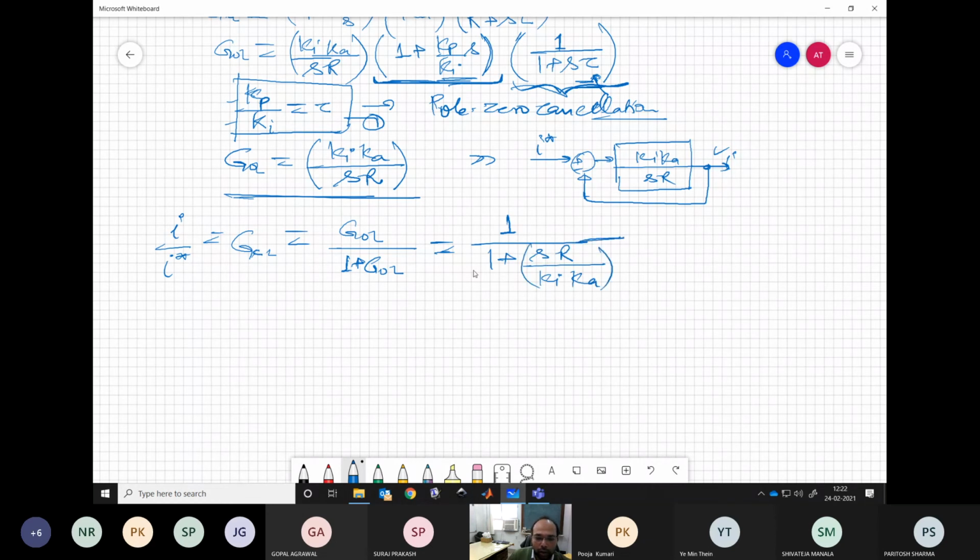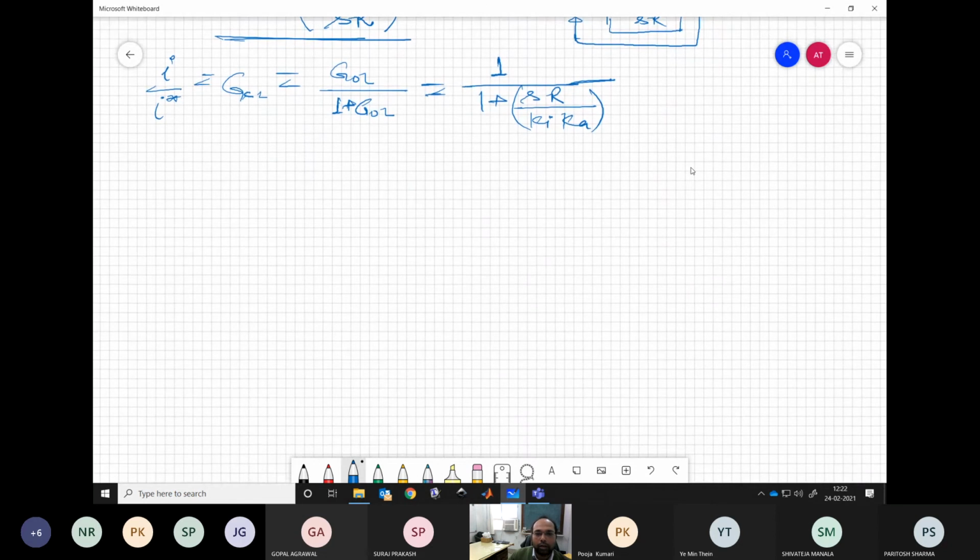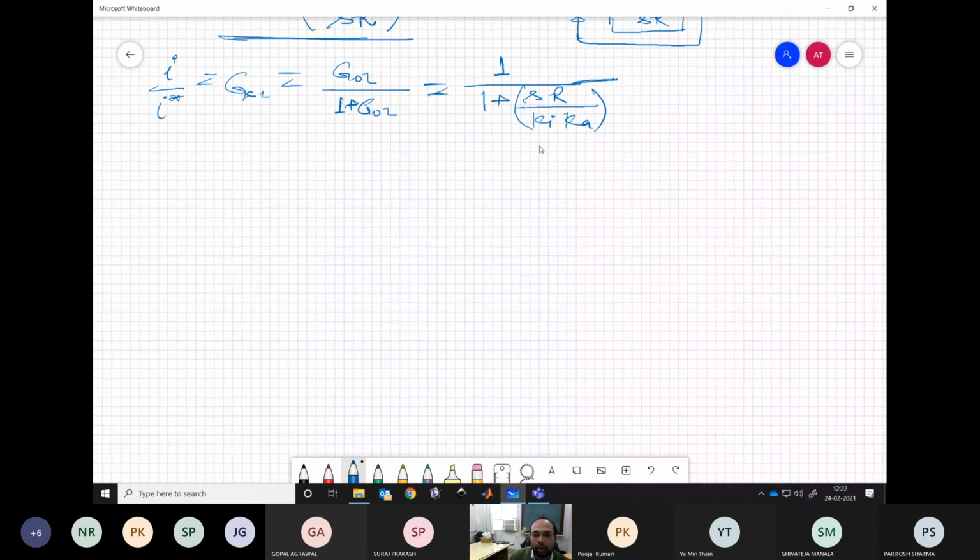Now, this is what we are trying to achieve, which means a good bandwidth. So how do we decide what the bandwidth is? Let us say we go for the Bode plot, only the gain is sufficient to tell what will happen. So let's say this is your 20 log G. So for this system, we know that initially it is only this constant K, which is 1, coming over there. So our plot will start from the 0 dB line.